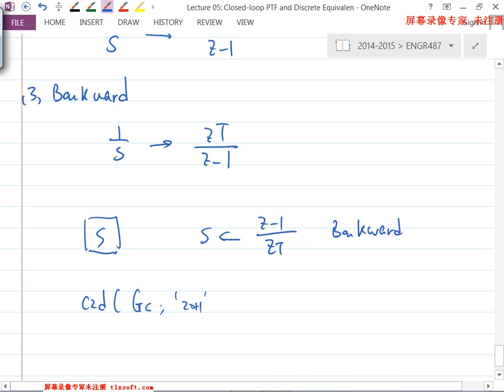There's a zero order hold in front of the block, right? Yeah. And if you put this one here, now what we call it is Tustin. Okay? So you basically get what I just showed you there. Basically the S is being approximated using the Tustin method. Okay? Yeah.